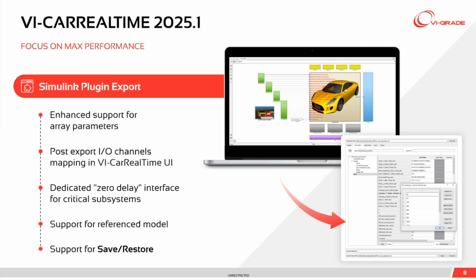In addition, with the introduction of the support for reusable code, it is possible to use the same component multiple times in a single VI-CarRealTime model, and it is possible to use interactive connection of I/O channels in VI-CarRealTime to connect the several plugins at once to the same model. Another interesting feature is the zero delay interface that we created for subsystem, where even a single step of delay introduced by the co-simulation may be critical for stability reasons.